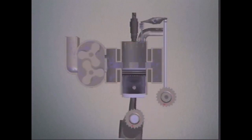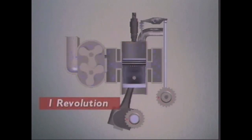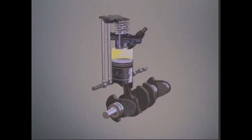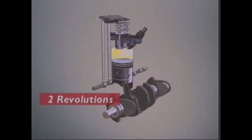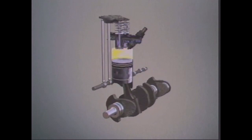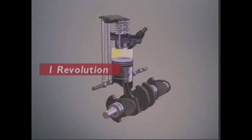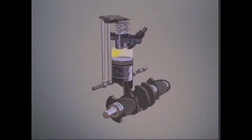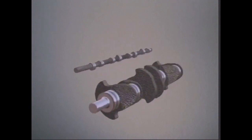In one two-stroke engine cycle, the crankshaft makes one revolution. How does this compare with a four-stroke engine cycle? How many revolutions does its crankshaft complete from intake through compression, ignition and power to exhaust? It makes 2 revolutions. In that time, what happens to the valves? They open and close once. So the cams must make just 1 revolution, and if the cams make 1 revolution, so must the camshaft. But in each four-stroke cycle, the crankshaft rotates completely twice, so the camshaft must rotate at half the speed of the crankshaft.